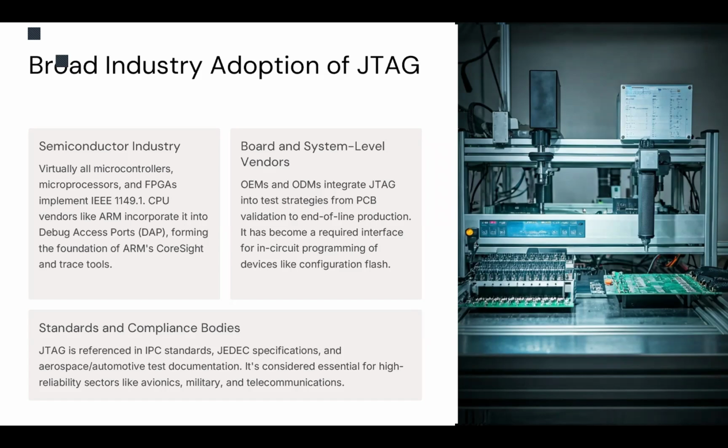It's also used for in-circuit programming of non-volatile devices such as flash or EEPROMs. So as a result, JTAG became a very important and essential tool for maintaining quality, reducing cost in high volume production, and validating the performance and the quality of the product.